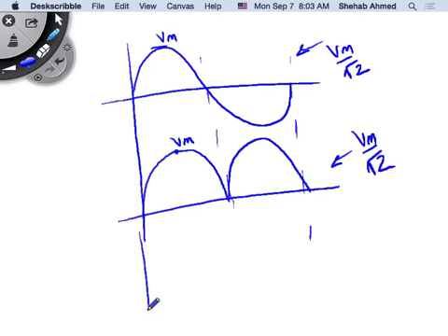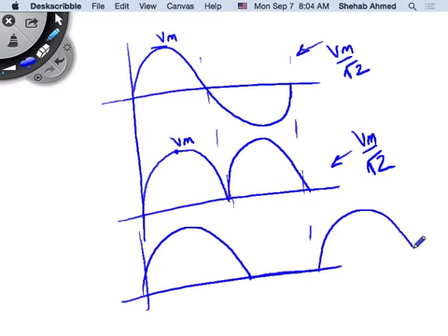And then we did it for the half wave. So this is called the full wave rectified waveform. This is called the half wave rectified waveform. We did this as well, and we said that this has half the area under the root, right? So V max over square root of 2 is the RMS value of the sine wave, and this has half the area that we're talking about for the sine wave or the full wave rectified waveform.